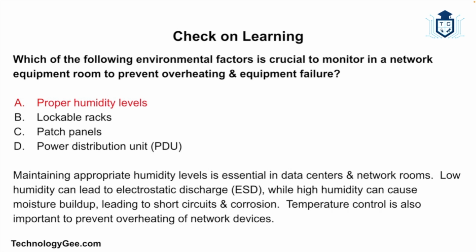Maintaining appropriate humidity levels is essential in data centers and network rooms. Low humidity can lead to electrostatic discharge, also known as static electricity, while high humidity can cause moisture buildup, leading to short circuits and corrosion. Temperature control is also important to prevent overheating of network devices.